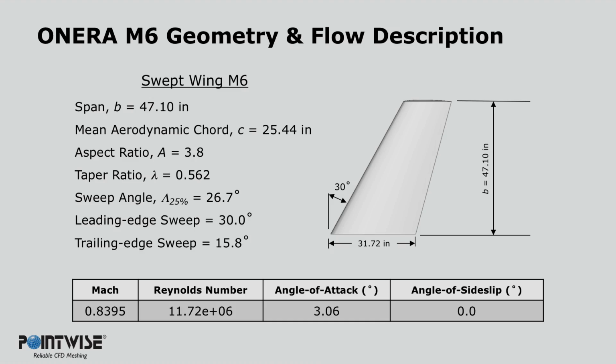To demonstrate how this process works, I'm going to walk through the process of making an initial coarse mesh in Pointwise to solve for the flow around an Onera M6 wing using the adjoint-based adaptation mechanics included in NASA Langley's FUN3D flow solver. By starting with a coarse grid and scheduling successive limits on the grid complexity, the execution time on initial grids can be reduced. The control Pointwise offers its users and its ability to resolve highly curved surfaces using anisotropic cells are extremely valuable in creating a coarse mesh while still resolving the analytical features of this geometry.